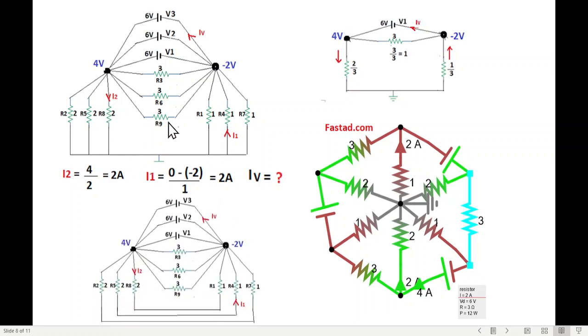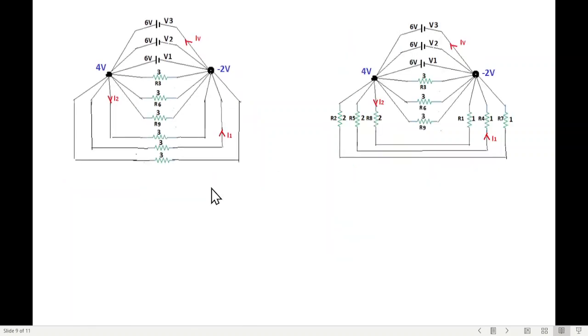So this then helped me guess the technique, and that is that if we connect these two also in parallel with this, then we can have the desired result. And let's see how that is possible. Because you see, this is 6 volt. To get 4, we have to divide it by 1.5. And how can we get 1.5? If we have 2 resistances of 3 ohm in parallel. So let's see next.